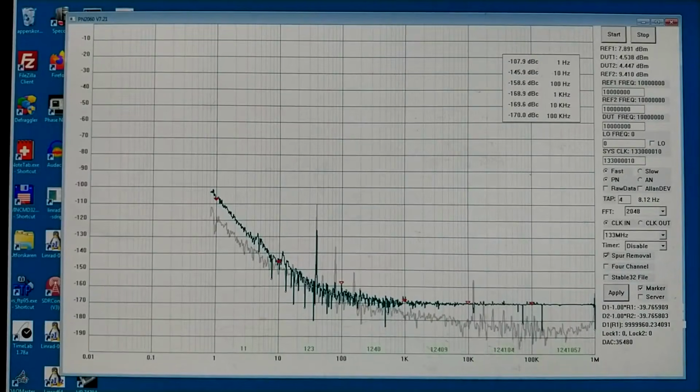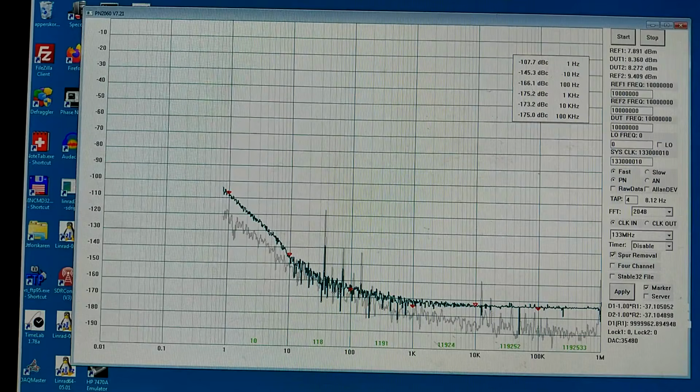Maybe I have placed the resonance far too close to the series resonance, or maybe the transformer is noisy. It is from 61 material, while the previous transformer was from 67 material. Otherwise, there are no changes and the signal level in the amplifier is as before. And I have not seen any parasitic oscillations. I made a new transformer on a 67 core, this time 4 plus 8 turns with a somewhat thinner wire, compared to 3 plus 6 turns on the 61 core.